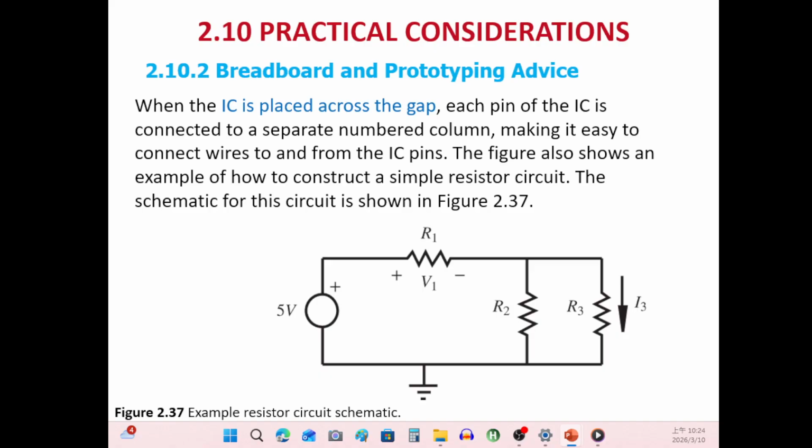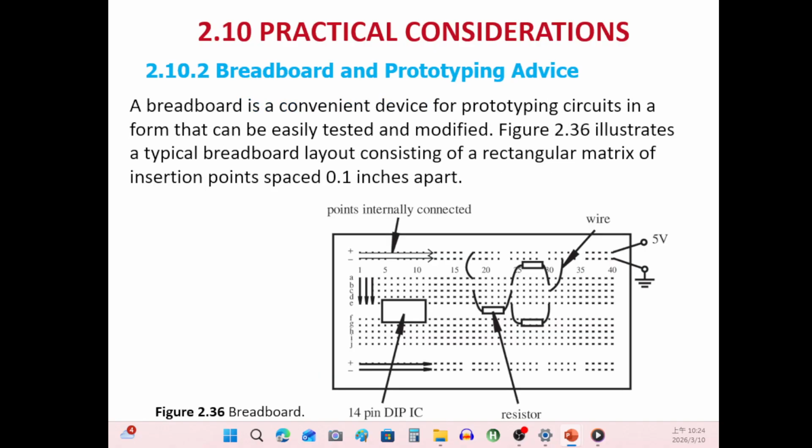One voltage source and R1 are here, and R2 and R3 are connected in parallel. Let me show you how to connect this on the breadboard. First of all, there are 4 parallel lines. We call it the power bus.